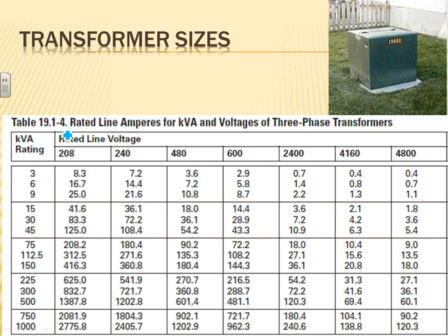What this helps you is they take all the most common transformers and they give you the full load amps for them. For example, here's my 30 kVA transformer, very common. At 208 level, it will give you this amount of full load amps. At the 480 level, which is the primary side of this transformer, it will give me this amount of amps. So these are no rocket science. They take the kVA divided by the voltage, primary or secondary, and 1.73.